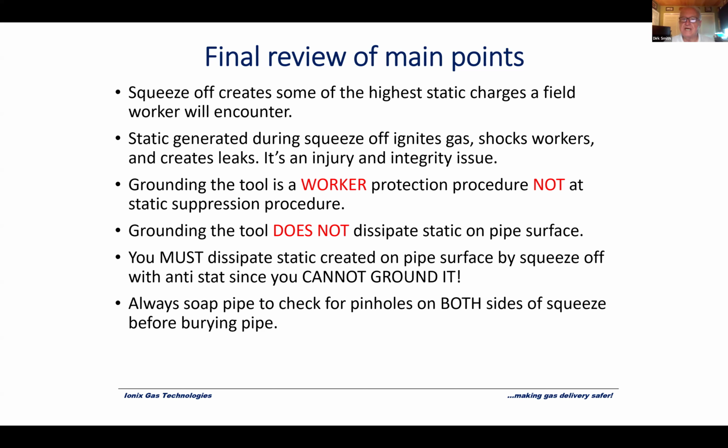Grounding the tool does not dissipate the static on the pipe surface, and it does not dissipate the static inside the pipe, as James was asking about. You must dissipate the static created on the pipe surface by squeeze off with anti-stat, because you can't ground it. In other words, the grounding tool will not do that. And always check for pinhole leaks on both sides of the squeeze off before burying the pipe.